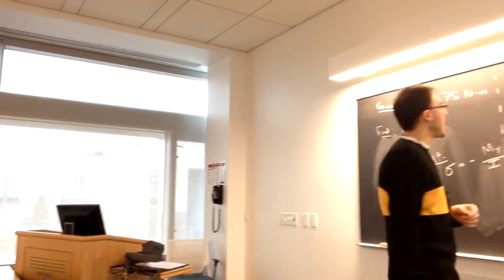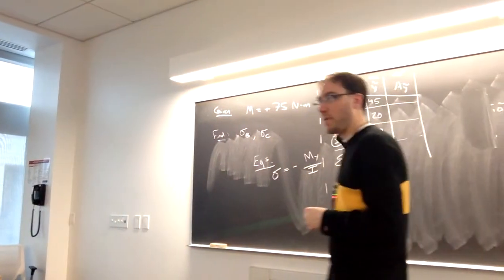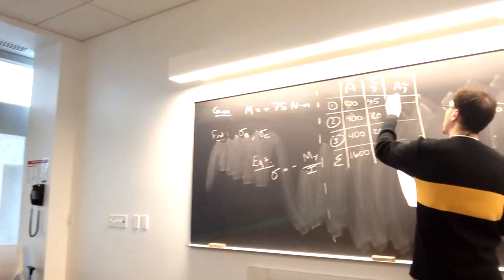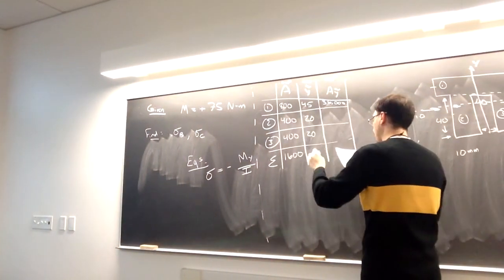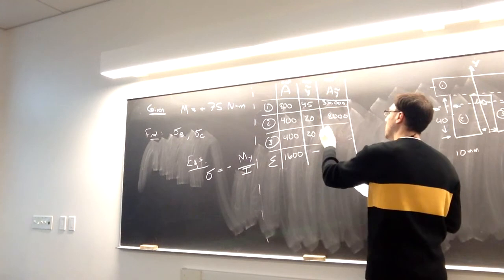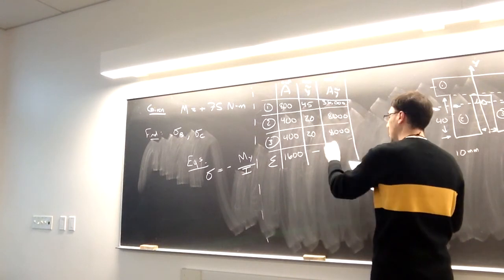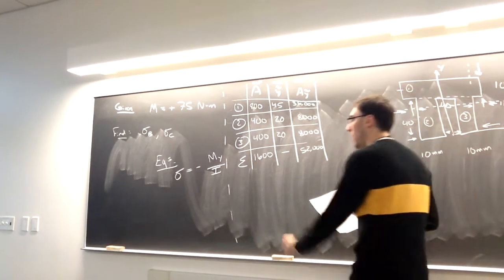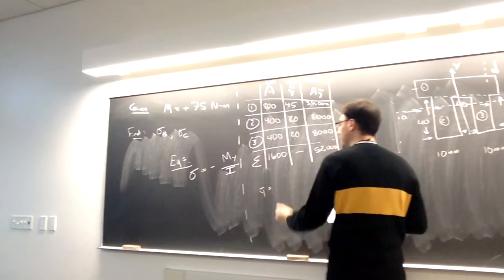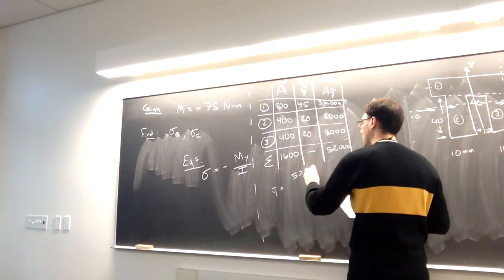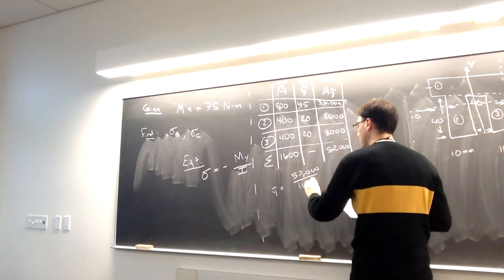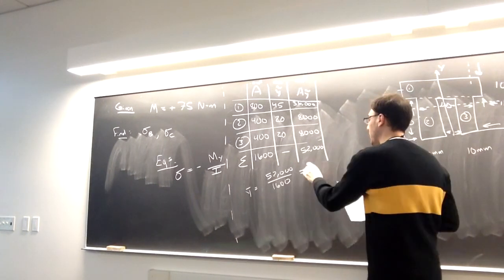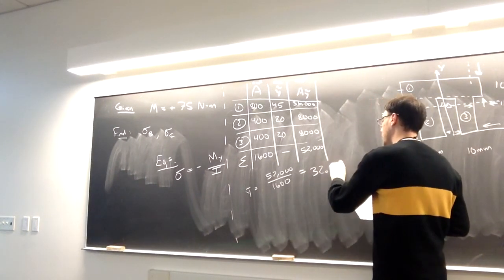Last step, I multiply A times y tilde across my rows. So I get 36,000 and 8,000 for the other two. And to find y bar, the location of that centroid, it'll be 52,000 over 1,600. Y bar is going to be 32.5 millimeters.